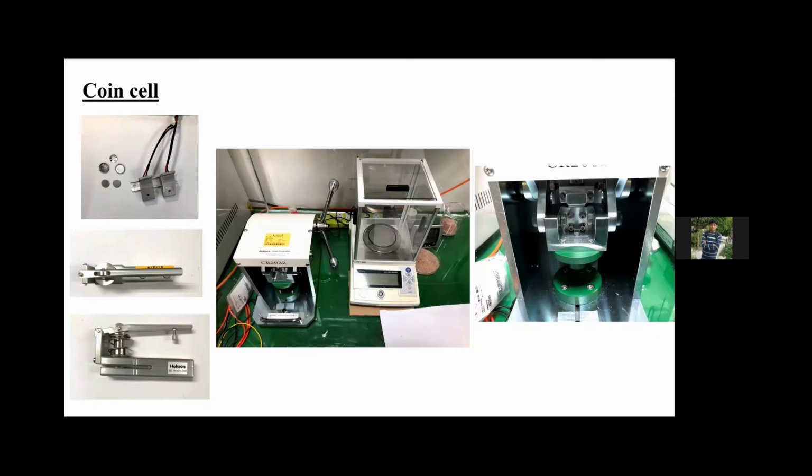And how to assemble? Before assembling, the first thing is, because we need to calculate the specific capacitance, if we calculate the mass specific capacitance, we need to check how much material is deposited, in the case of the positive electrode and the negative electrode separately. Now, consider that the mass and charge are all balanced, and we make the thin film and cut it to this diameter ring.